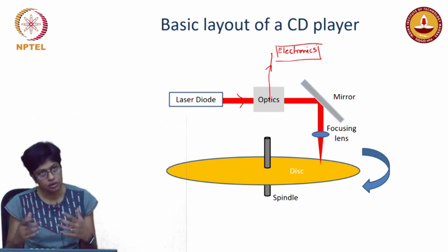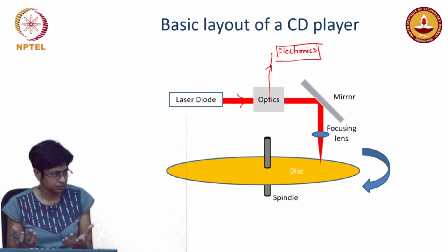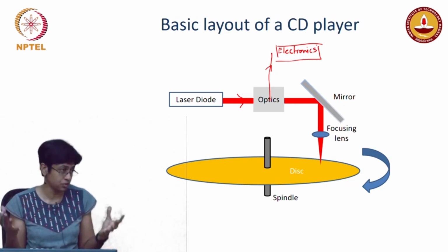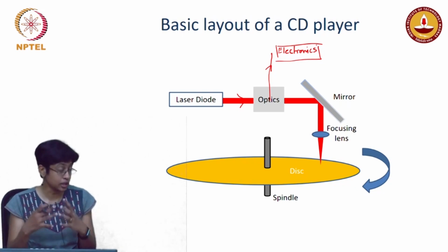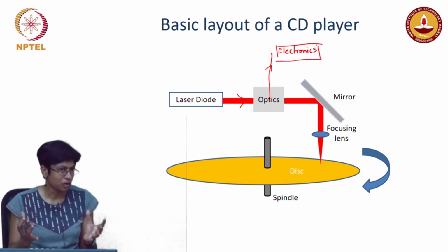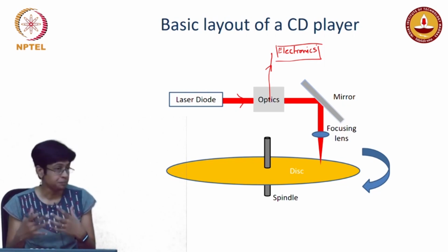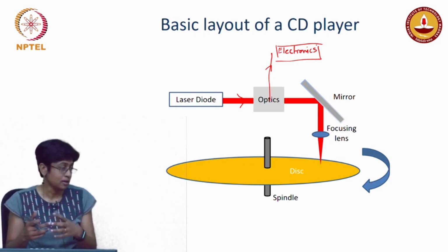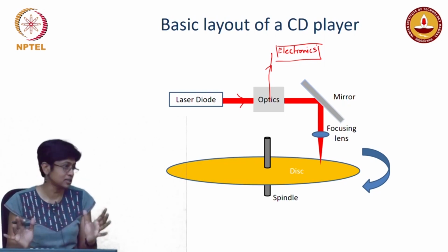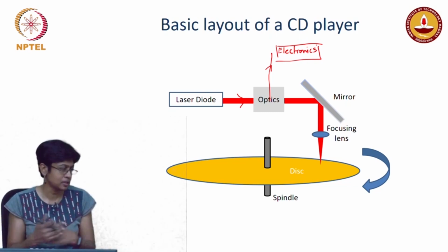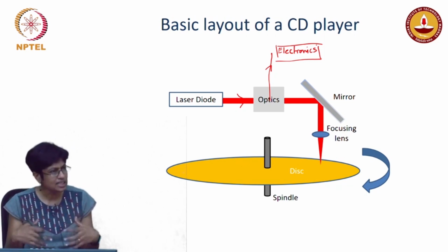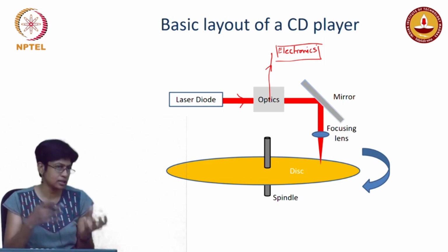But we have a lot of information that we want to convey. So that's a very bulky way. If you want to convert a large volume of data into just ones and zeros, you're creating a very large volume of ones and zeros. So it's not a very efficient way of storing information. Plus, finally, when you say light reflects off this disk that is wobbling, how do you decide what is 1 and 0? If there's a clear system, there's no noise, you might say, yes, it's obvious. What about in a system where there is noise? I'm putting some threshold and saying above this is 1, below this is 0. So you want to have slightly more sophisticated ways of imposing that information onto light.